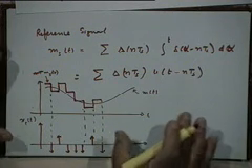Yes, please. So isn't there a loss of information in this case? Yes, there is loss of information. If in the time interval in which we take these samples m(t) changes by a large amount, then you cannot map the amount of change in m(t), whether positive or negative. We'll discuss all these issues. Just let's go through the process of understanding first. You are right, there is a loss of information. Any process which represents analog information as digital information will have some loss of representation. The only thing is we like to make that loss as reasonably small as possible, and we will have to see under what conditions that will happen. Those are the things we need to understand. But let's go through the process first. Okay, so is the process understood?